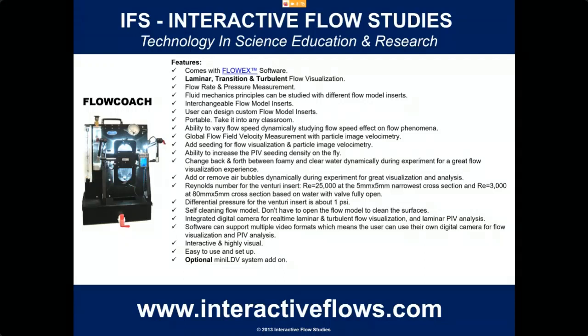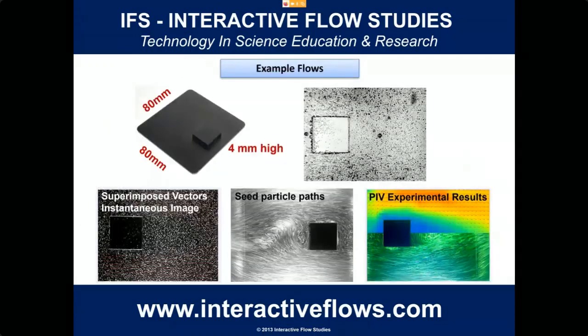Integrated digital camera for real-time laminar and turbulent flow visualization and laminar and turbulent PIV analysis. Software can support multiple video formats, which means the user can use their own digital camera for flow visualization and analysis. It's interactive and highly visual. It's very easy to set up. And one more feature is you can actually add a mini LDV system to it too, to make it even more accurate. Now here are some of the results that we have from FlowCoach.